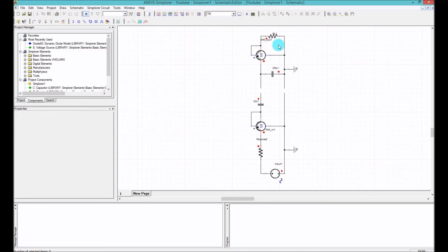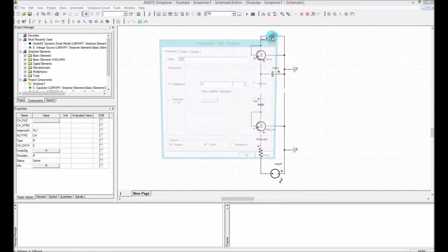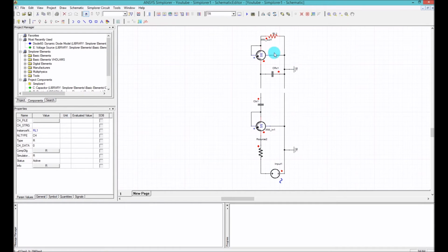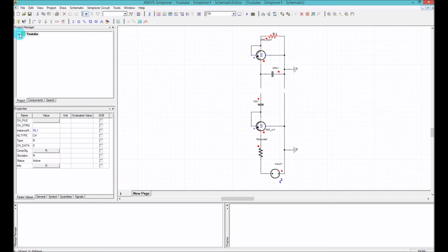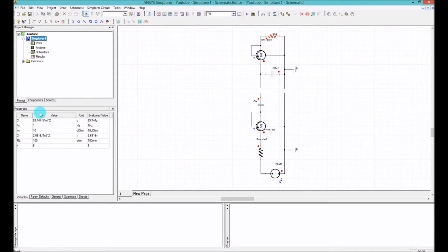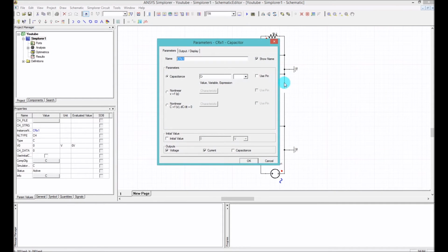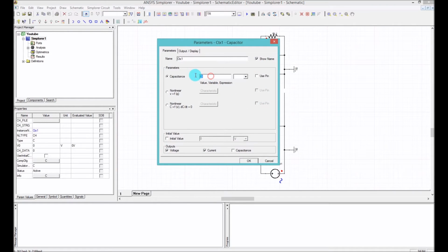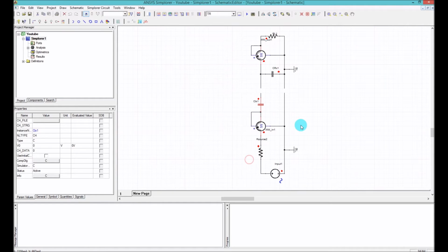So on the top here I have the value for my resistor. I put a resistor with the value RL, which I can change whenever I want. I defined RL to be, I think, 100 ohms. I have my RX resonator capacitor CR, and I have my TX resonator capacitor CT. I have a wattmeter and also a series resistance in order for the calculation to work.